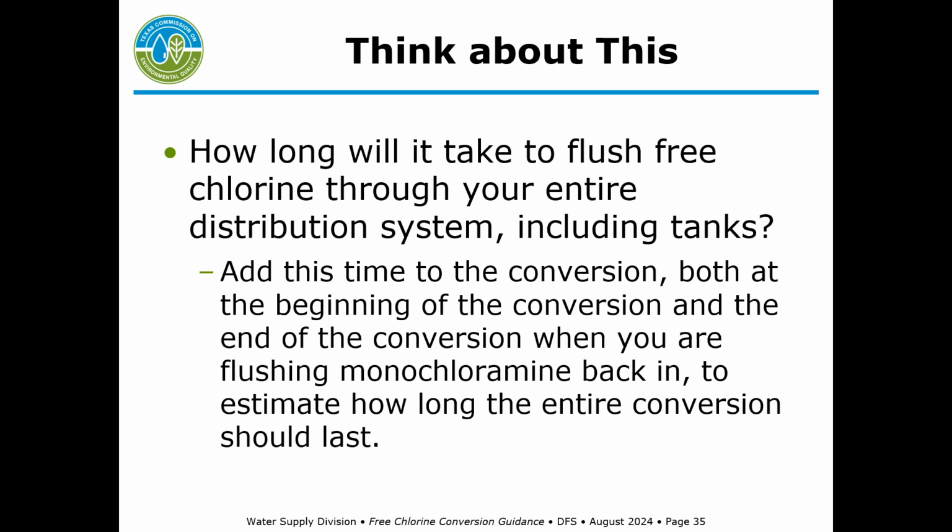How long will it take to flush free chlorine through your entire distribution system, including tanks? It's going to vary by each system, so you're going to have to kind of figure that out. The key is add that amount of time at the beginning of the conversion, and remember, at the end, you're going to flush monochloramine back in, so you need to add the times both at the beginning and the end of the conversion, and then estimate how long you need the entire conversion to last.